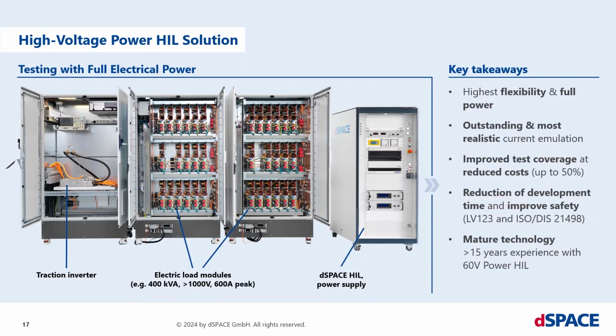So for example, if you want to set up your power electronics device, but the machine is not available in that early stage of the development process, you can emulate the behavior of your machine if you have the model parameters and test your traction inverter even if your machine is not available at that point.